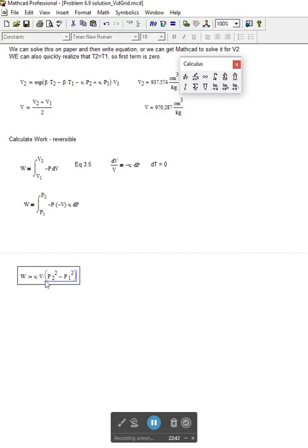And so I selected that whole thing. The parentheses help me do that. You can put a lot of parentheses in, or you can just use MathCAD selection to put parentheses in automatically sometimes, however you like to do that. That's my equation for work. Again, remember I used the assign, so that's colon. Now I want to actually print out the value of work. And so that's work and then just the plain equal sign.